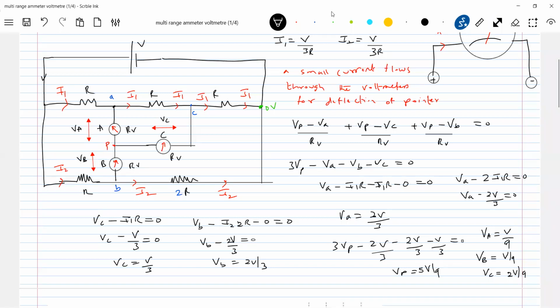If it doesn't ask for any reading of the voltmeter and says ideal, then you have to replace it with an open circuit. We have to be alert with numericals like that. If they ask in advance, they will use words like "very high resistance" rather than saying ideal.